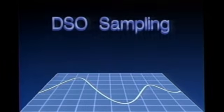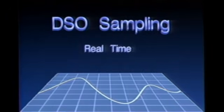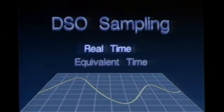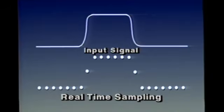As we said earlier, sampling is the process of obtaining the value of an input signal at a specific point in time. There are two major categories of sampling: real-time sampling and equivalent time sampling. In real-time sampling, all sample points for a waveform are obtained in a single pass. Because samples are taken all at one time, the sample rate must be sufficient to collect enough points for faithful reconstruction of the input signal.